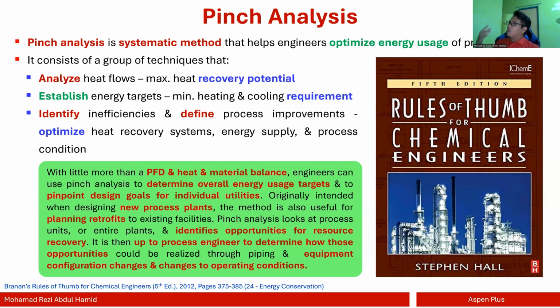For example, stream 1 cannot exchange heat with stream B, even though in theory it can be done. Maybe there's not enough space to put a line, or maybe those particular streams have corrosive properties. If you do heat exchange between stream number 4 and 5, an explosion can occur, or maybe your boss simply does not want that heat exchanger because of some weird reason.